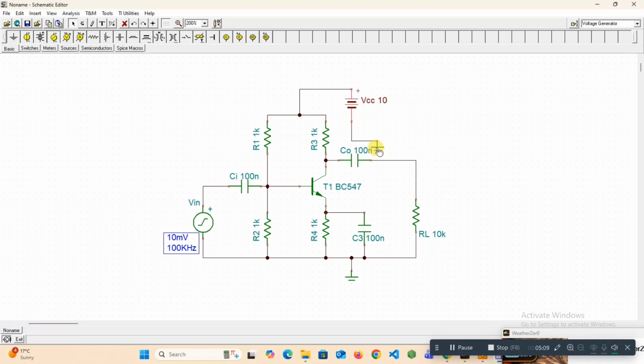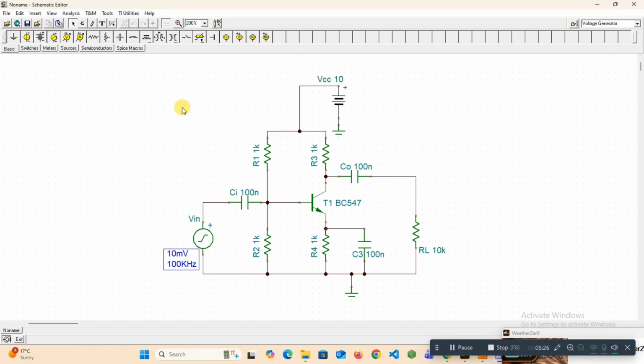And then I'm now connecting output voltmeter in parallel with the RL. So where I'll get the output, and now I can see how my input waveform and output waveforms are amplified. But you can see that waveforms are inverted, 180-degree phase shifted. Why? Because NPN transistor acts as an amplifier but will give you inverting signal. Why inverting? That is because of the load line. So we will see that in a next video. Stay tuned for that.